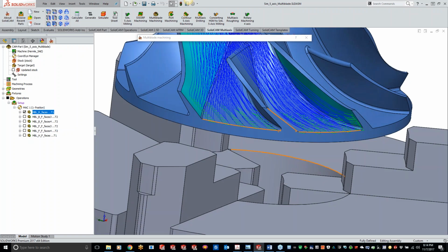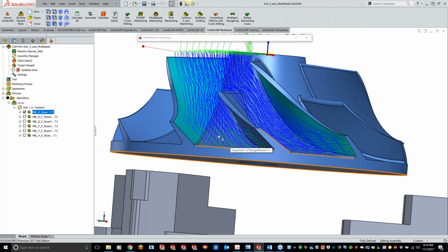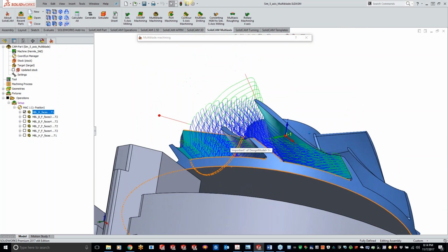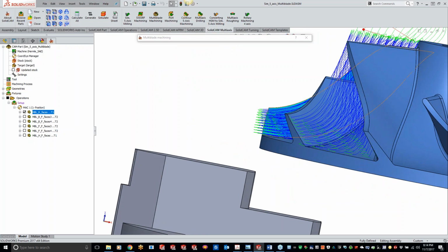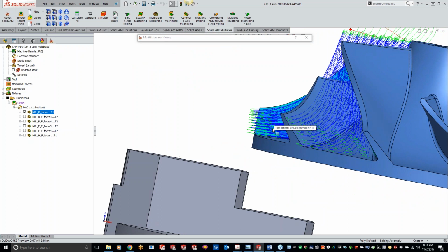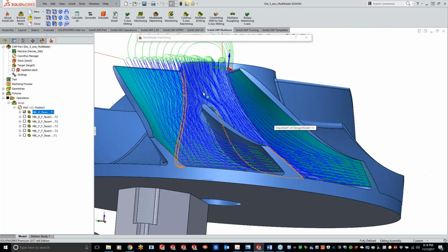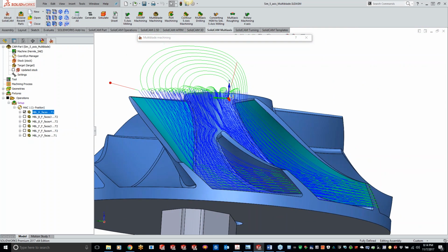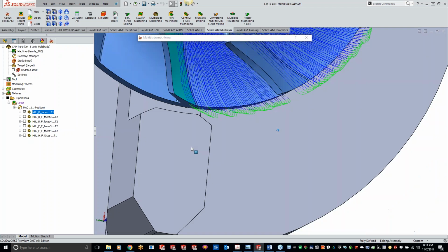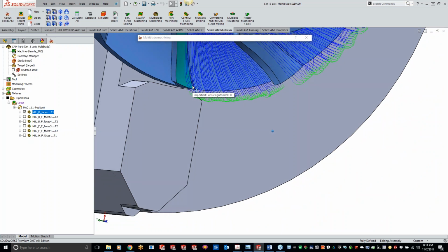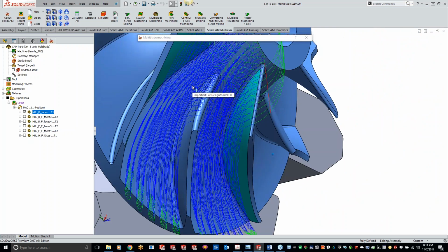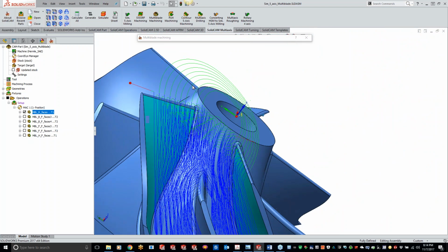So here's our multiple passes coming in there, and you can see it's not cutting air at all. If we do a side angle here, keeping down in that stock, stepping down what we've told it, going all the way down through there, kind of getting all that material roughed out for you. Nice lead, doing arcs going around and then coming back in the material. Same thing coming in down here, arcing out and then coming back in, keeping that tool nice and smooth throughout that pass. Hopefully get a good shot for you guys here.